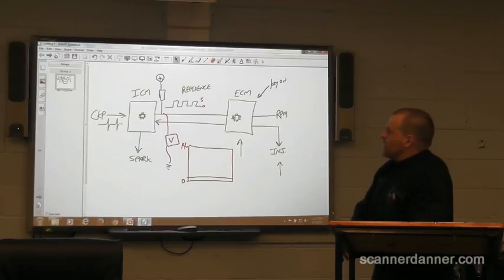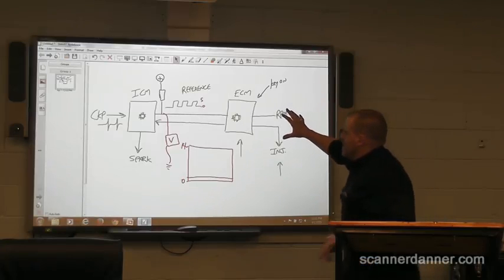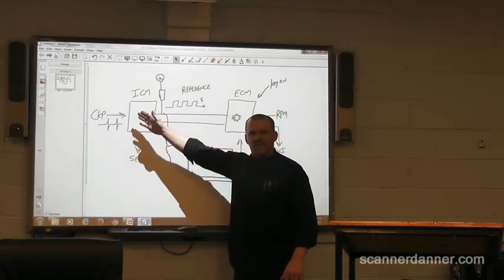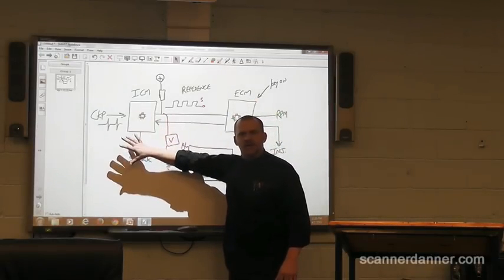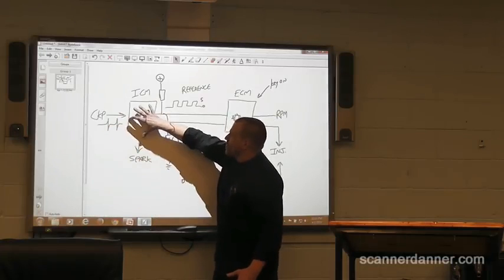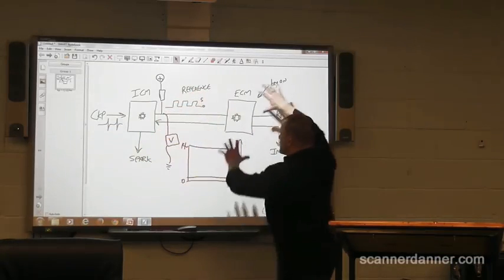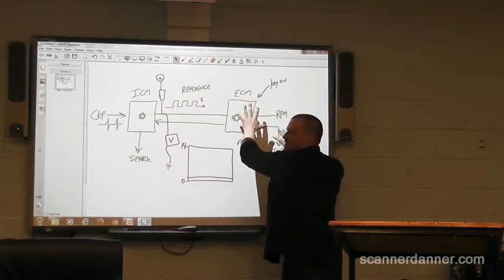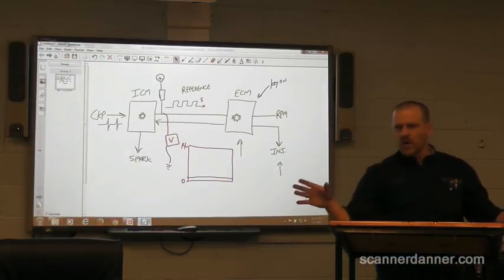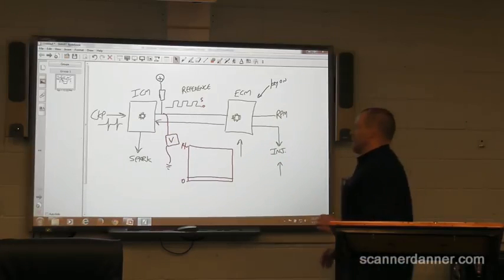Okay. If I did that test and it didn't react, I had no reaction over here, does it make sense that I wouldn't turn left and focus over here? Because I'm creating the signal that the crank and module together would create, which is this square wave. I'm creating that signal and nothing's happening over here, so my focus is over here, not over there. Two completely different directions we go with one simple click of the test light.